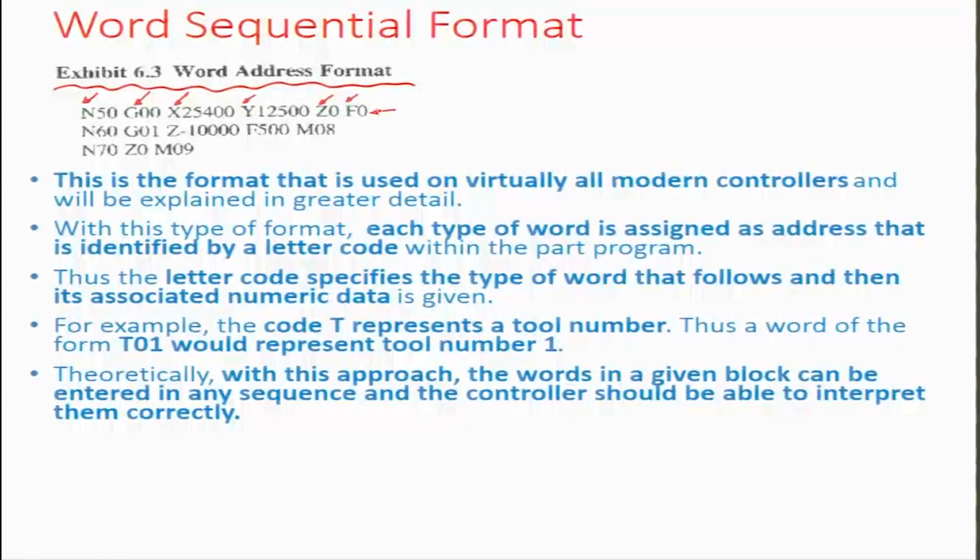So many words have been now put in instead of just numerals, and the advantage that such a representation has is that every time you do not have to refer as a programmer to the column header, or particularly for long programs, this is a big issue that the column headers have to be referred again and again, and it may not be on the same page. So this format changes the overall level of the inconvenience of usage related to CNC programming. So this is a format that is virtually used by all modern controllers.